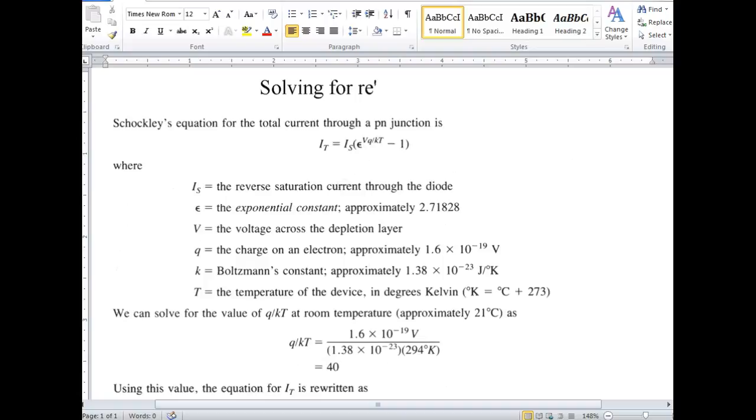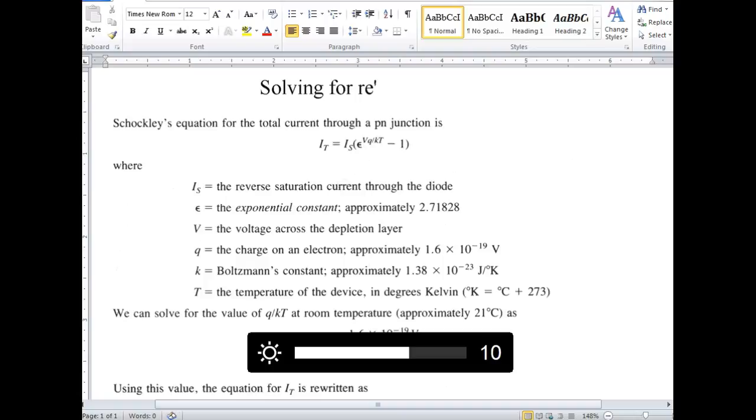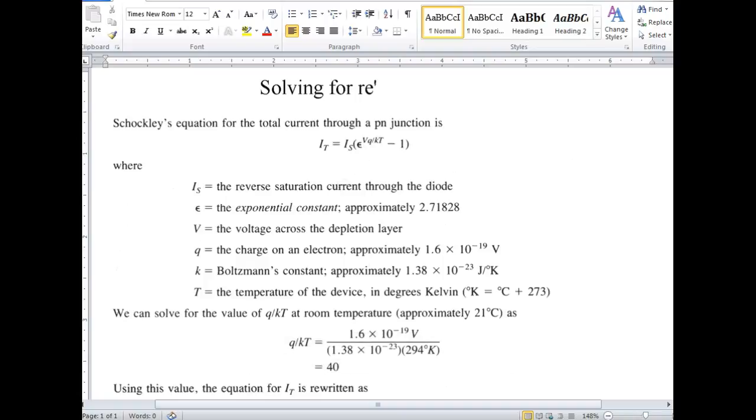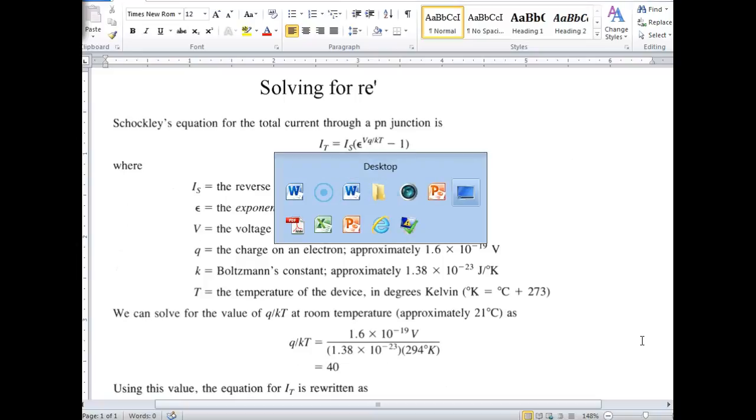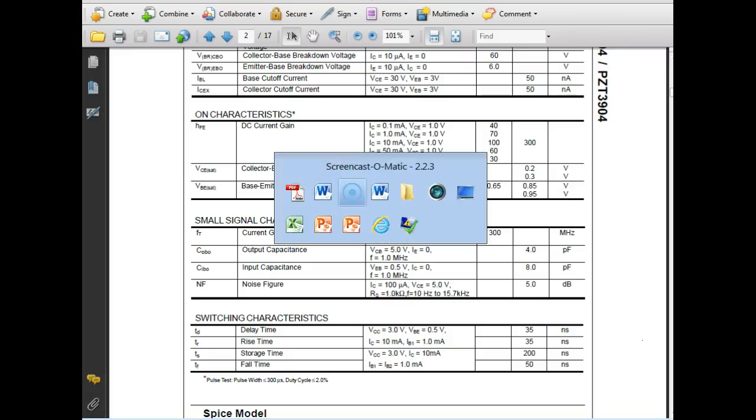Like I was saying, RE prime. So when we use DC, the RE, we're going to call it RE. It's going to be uppercase, right? You understand? RE prime is the dynamic resistance of a p-n junction. So we know from our diode lab and setting up that characteristic curve that when I forward bias a p-n junction, it is not a straight line, right? So what it does is it actually comes up and gives us a slant, right?